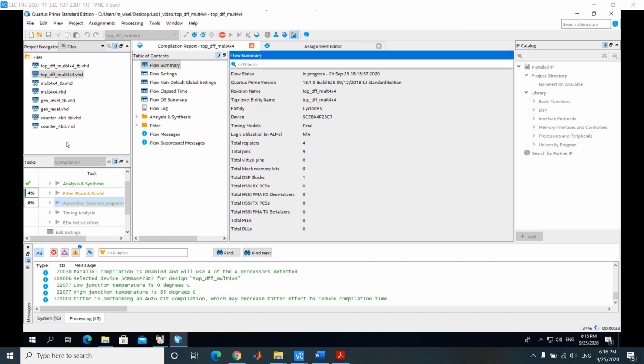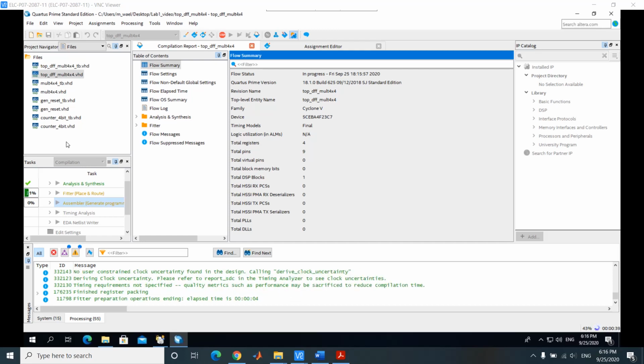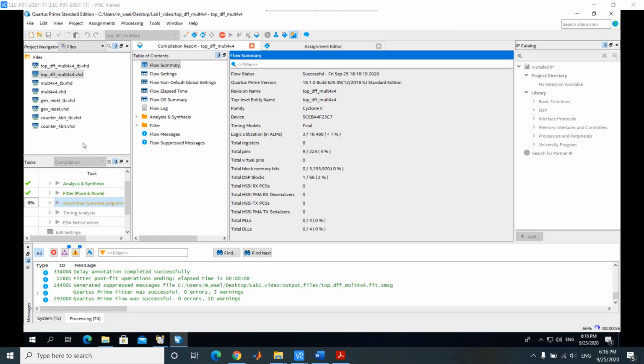In the .sdc file, you can define the uncertainty, and you can define certain other constraints on the paths, but since our design is simple, we are not going through many details in the .sdc file. We just create the clock and tell the compiler that our clock is the signal CLK clock.